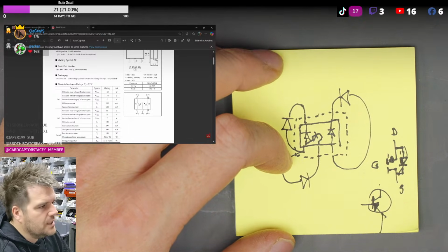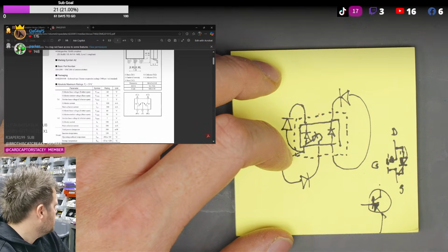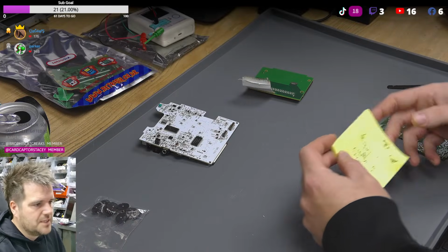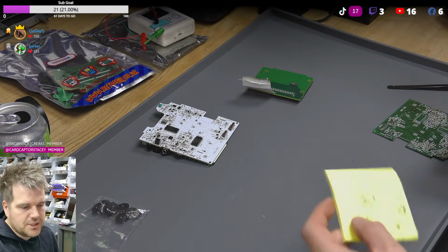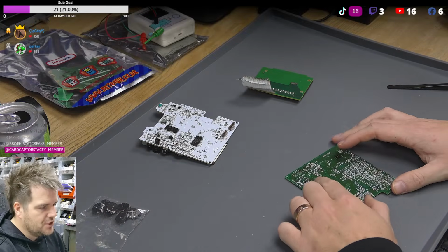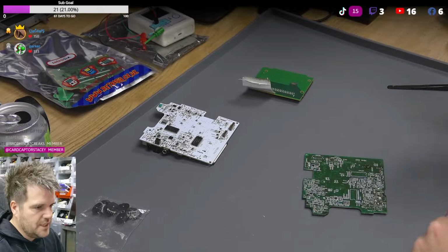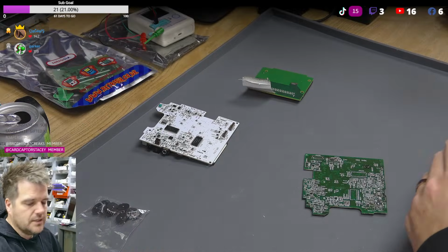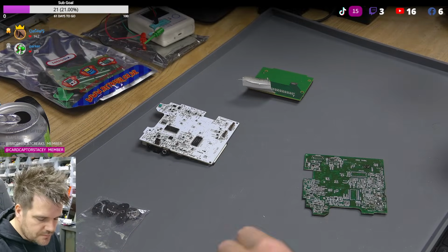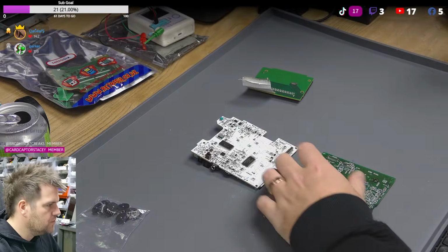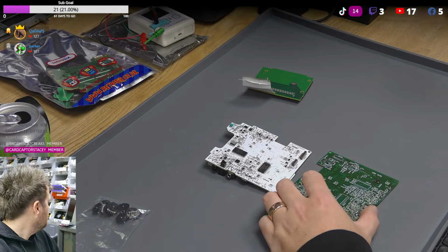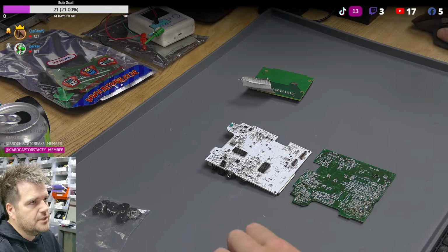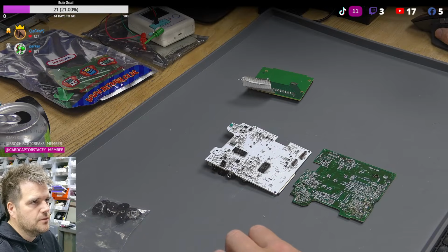So for now, I'm just going to leave this. I'll figure it out. I don't think you guys are that bothered if you see it being discovered. I'll tell you when I find it, but that's the process I'm going to go through. I'll keep looking for packages that look similar. I'll probably take this chip off and put it through the component tester in every orientation, and basically I'll figure it out that way. I'll find out there's going to be transistors in there. It's just a process of elimination and time. So for now, what I'm going to do is make sure I've got notes on the Excel sheet of all these parts we haven't identified yet, and then I'll come back to them. There's only like 3 or 4.